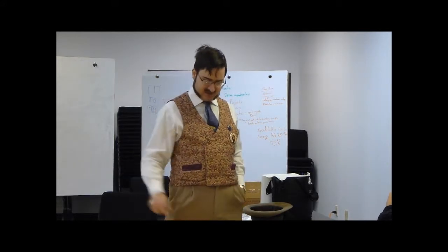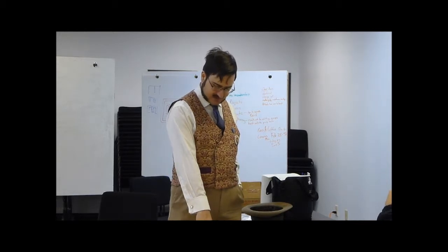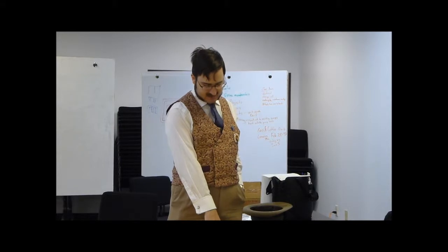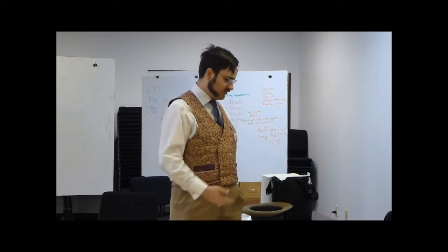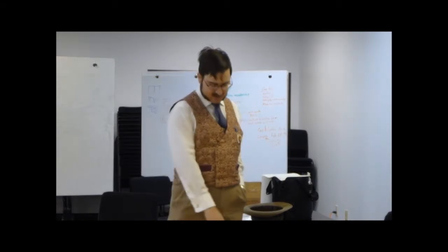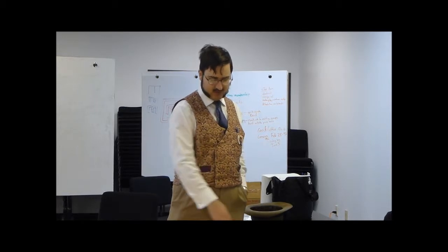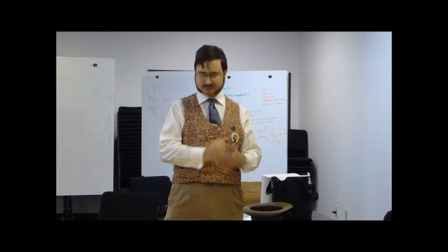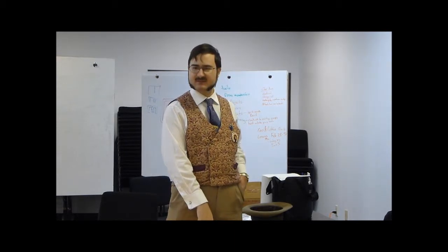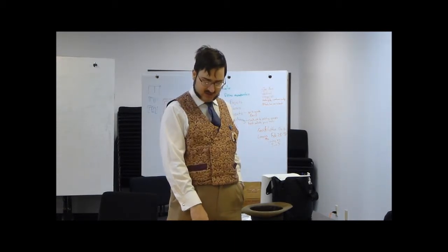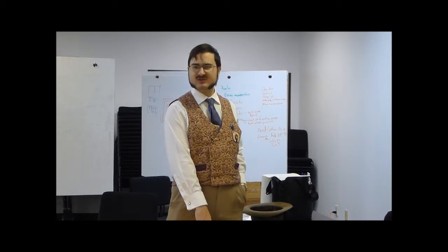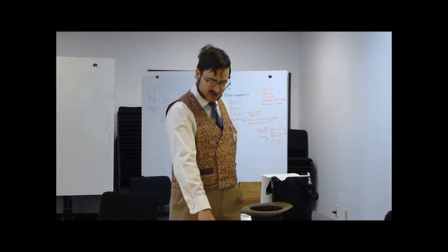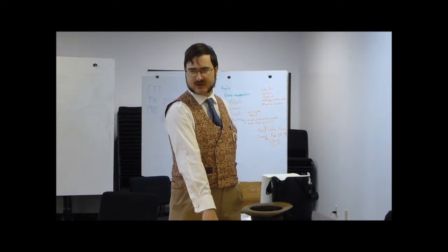So what happens? So an ionizing event, it's this tube. So this is the positive voltage. In this case, the spec sheet for this tube, which you can look at, but it's all in Russian, says 360 to 440 volts. In general, you operate right smack dab in the middle of that region. So we apply 400 volts up here. Now, of course, when the tube is not conducting, the megohm resistor does not drop any voltage. So the voltage here is 400 volts. The voltage here is circuit ground, right?